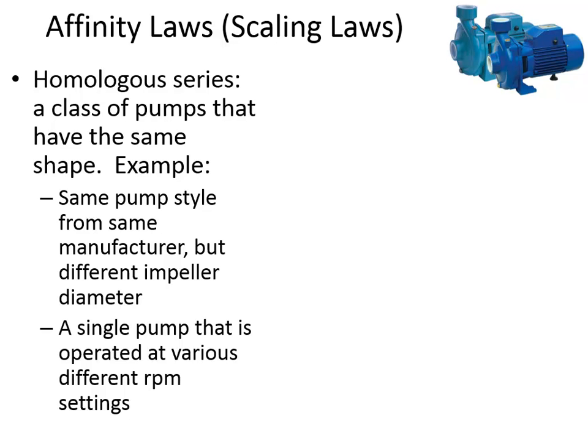All right. The next thing we're going to learn about are called affinity laws, sometimes called scaling laws. And actually, there's a series of equations in the FE packet that I just gave you of the affinity laws. What they're related to is the fact that sometimes manufacturers, rather than starting from scratch every time they design a pump, they'll use a similar shape, but they'll just scale up the size of the impeller and the pipe housing. And so they'll have these related pumps that are maybe a similar shape and performance, or sometimes you'll have a pump but you'll operate it under different conditions.